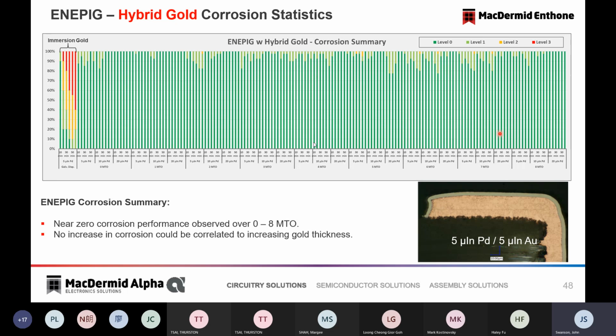So yes, you have a little bit of preferential, maybe some, I guess you could use the word, increase in voiding, but it's quite small, because the normal intent is to only put down, let's see, half a micron or 0.05 microns of gold, very, very small amounts. So I agree with your comment basically, but it's at a very small level.